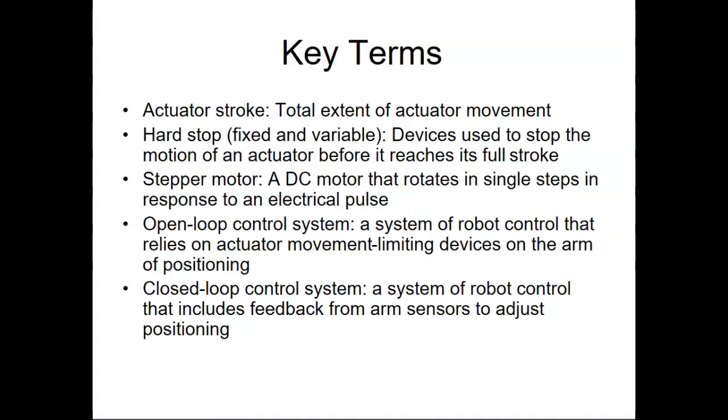What were you asking? No, what you're looking at with something like this is, let me see if I can draw it out for you real quick. So if this is your cylinder, okay? I've got it mounted to a line, but I don't need the full stroke. Instead, I'm going to put something like a hard stop or a variable stop so that when this guy extends, he can't go past here. That's what we're talking about with this, it's a way to stop it from fully extending and or retracting.